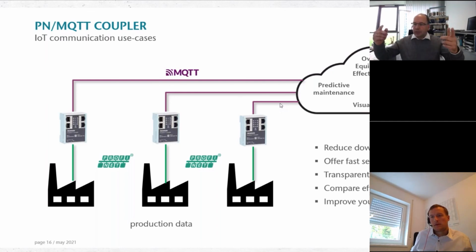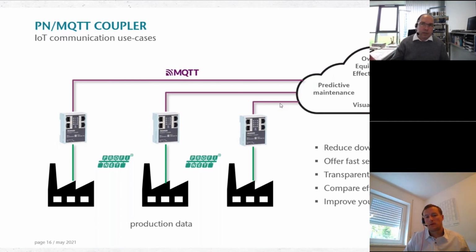If you go outside to the internet, there has to be a router, because the device itself has no ability to connect to the internet. So you need a router somewhere in the network, and in typical applications you put it inside the end customer network or the factory network, which is normally connected to the internet. It's a matter of router setup. You get the gateway information if you switch on DHCP, and then the device can connect. But you can also, for example, use the Rex 100 with LTE to connect to the cloud. It's no problem.